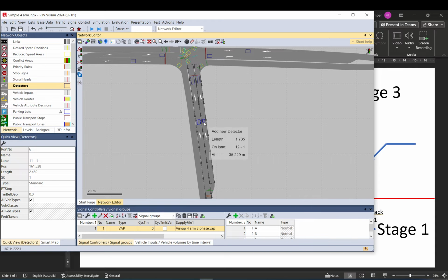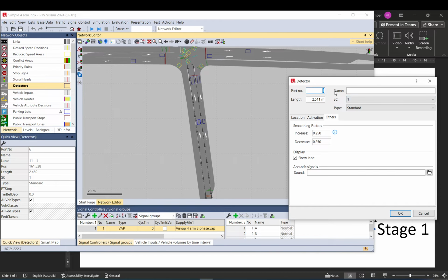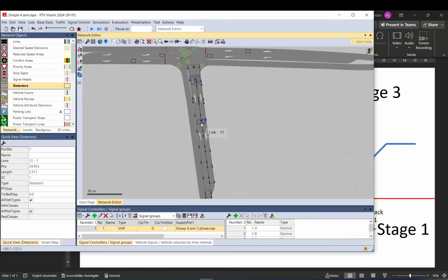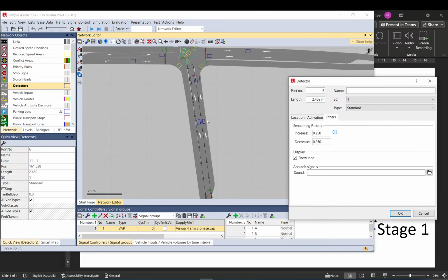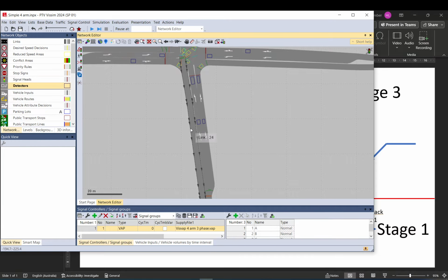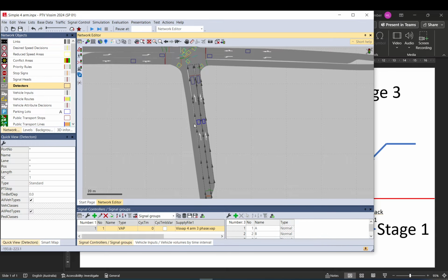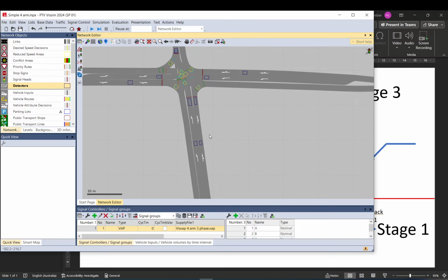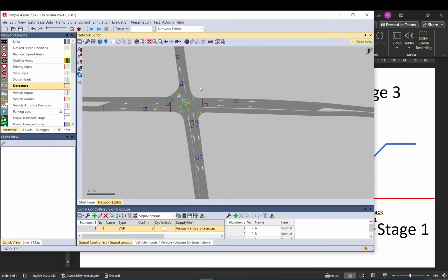So again, when I check for headways, I prefer to use separate port numbers, because when the port number is the same, Vissim assumes that they are in parallel, and I think it's safer to just keep it like this. So in case there is a vehicle on this one and then another one on that one, that is not something I want to pick up. I think it's better to just be safe and do two separate ones. So 5, 6, 7.